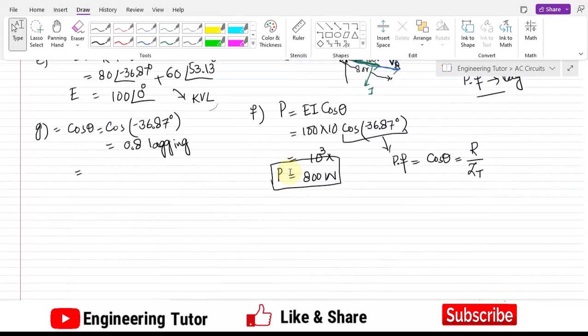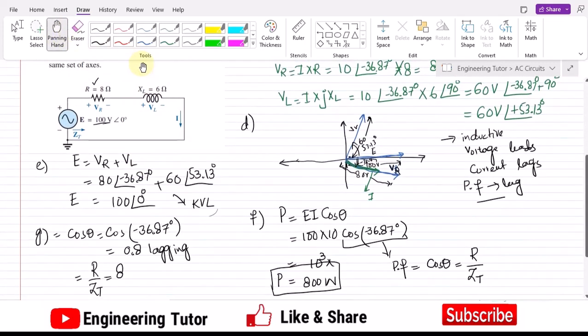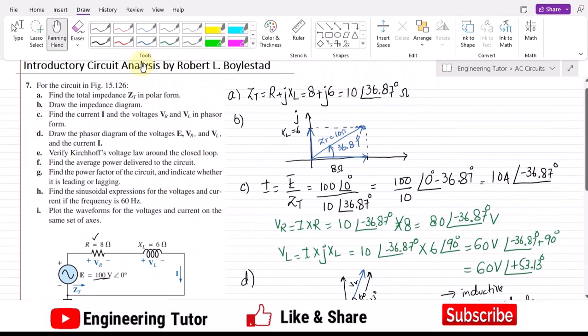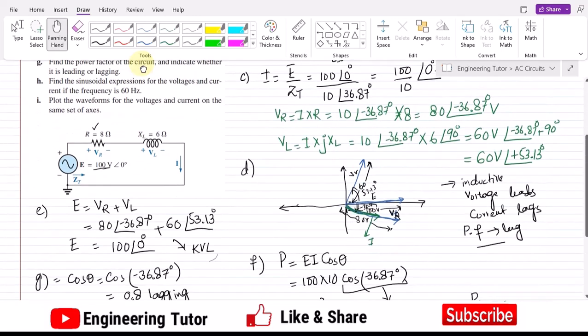Apart from it, as I have told you, power factor is always also equal to R divided by Z total. Okay, so the value of R which we have seen here is basically 8, because you may see from this circuit the resistance is 8 ohm, and the magnitude of the total impedance we have calculated is basically 10 ohm.